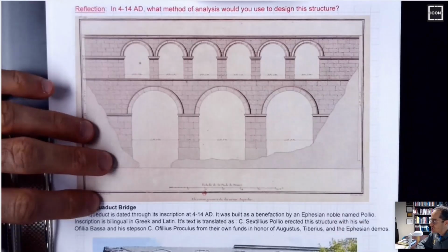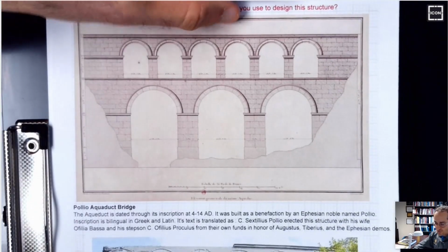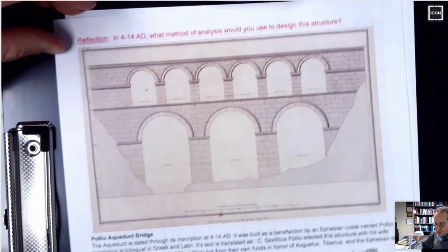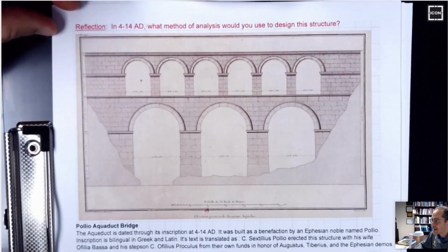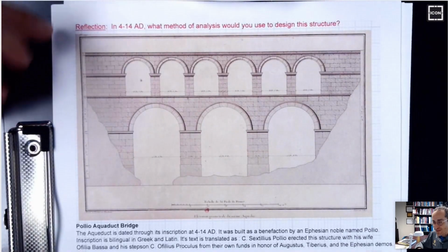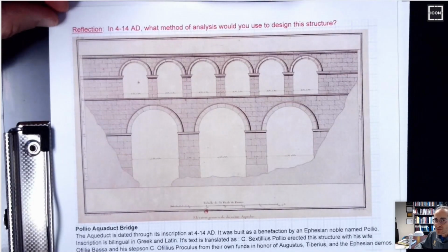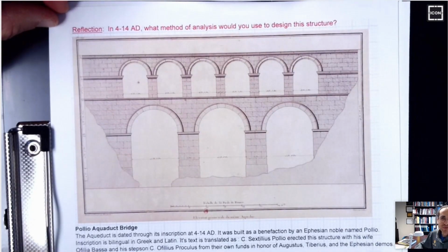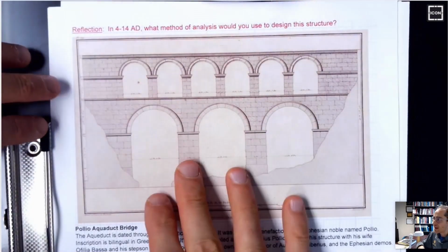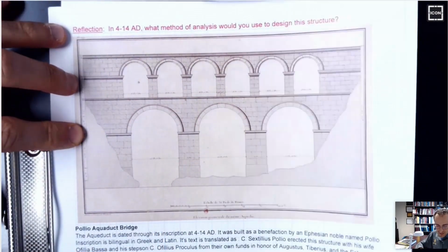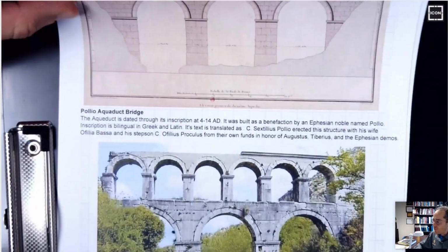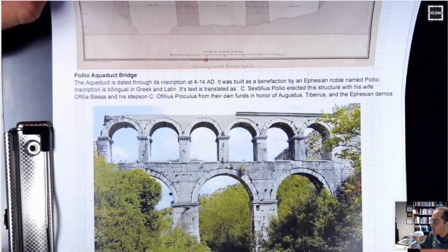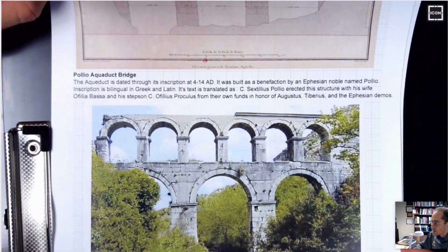My cover image is a historical structure. If you look at historical structures, you will see nothing but deep elements, because deep elements work efficiently. They are super easy to design, and you can just use a truss model to design these structures. So this is a very good candidate. If you have no computers and no advanced tools, you can use a strut and tie.